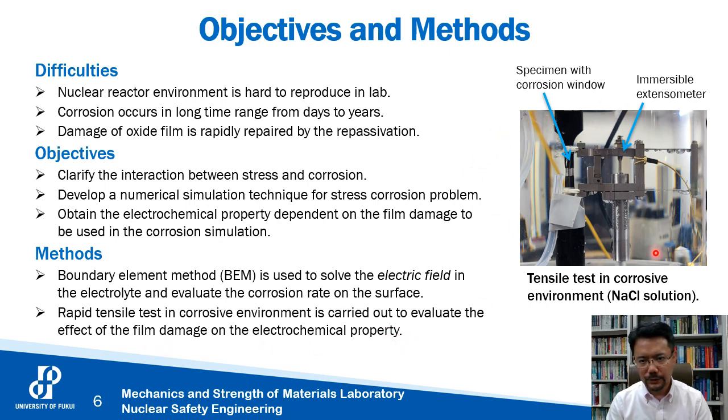This photograph shows the tensile test in the NaCl solution. This is the tensile specimen, and the black part is the coating. So only this part is exposed to the NaCl solution. And to measure the strain, we are employing the immersible extensometer like this.